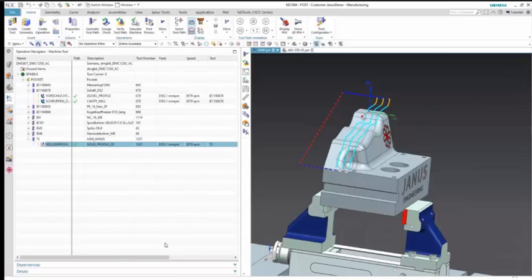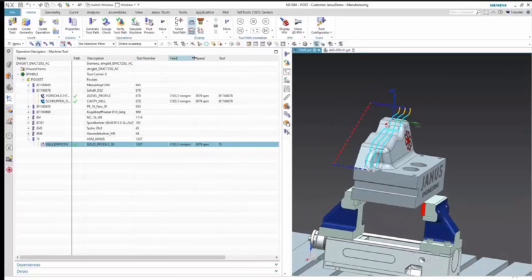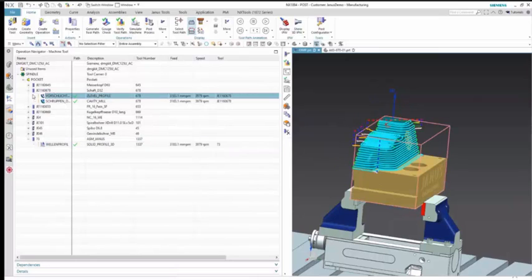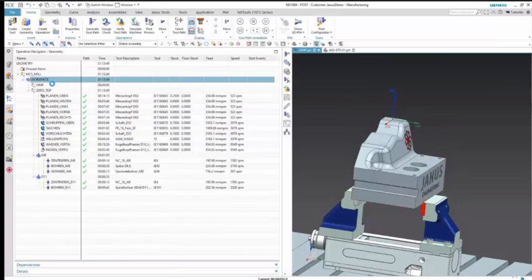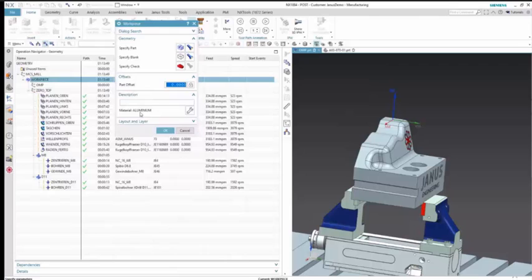But what is the problem so far? We are having a problem according to the feed and speed. When we take a close look at them, we see that the feed and speed of this tool for this part material, the part material, by the way, is being defined in the workpiece, and for now it's set on aluminum.